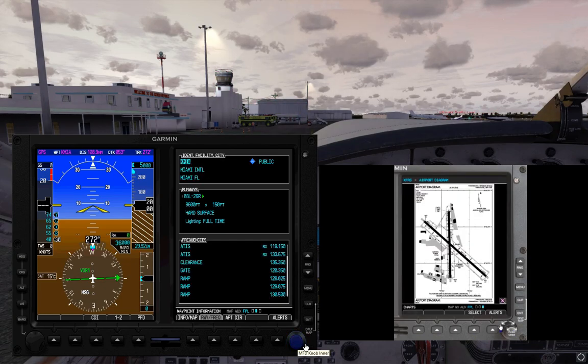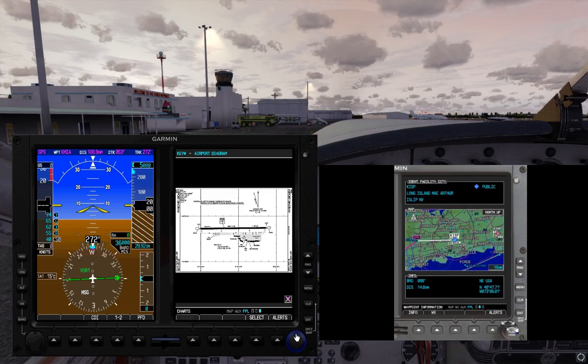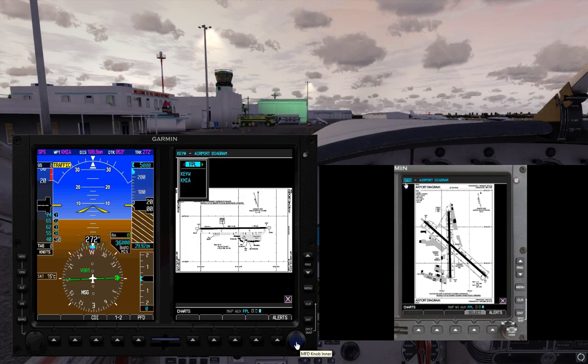The last page in the flight plan chapter is the charts page. We have the ability here now to see charts for any airport, and specifically for airports we're planning on using as we fly in our flight plan. So once I'm here, I basically push the cursor. I need to select first with this soft key the airport for which I want to have information presented. In this case, it's defaulting to the airport where I'm currently located and about to depart from.